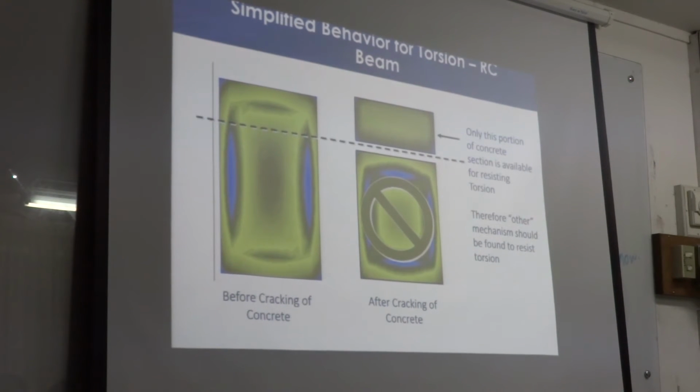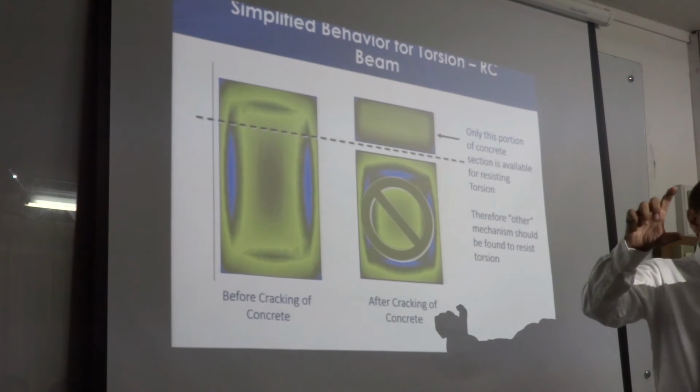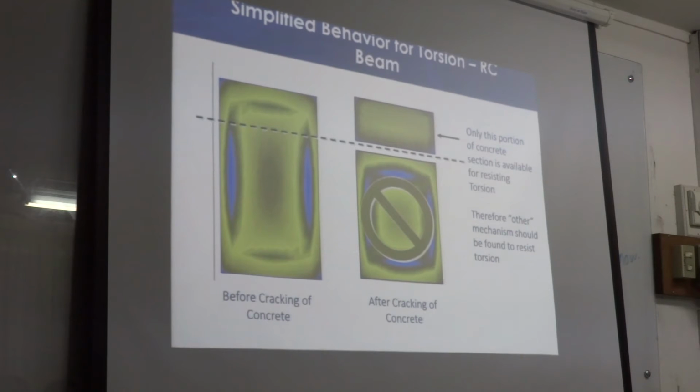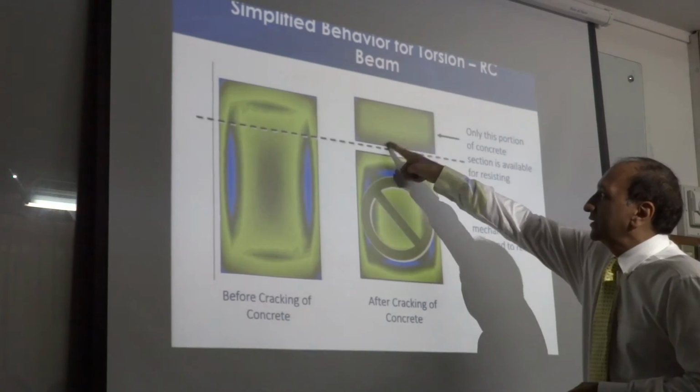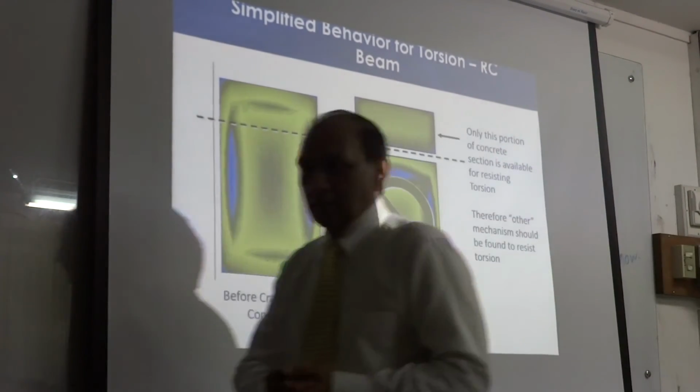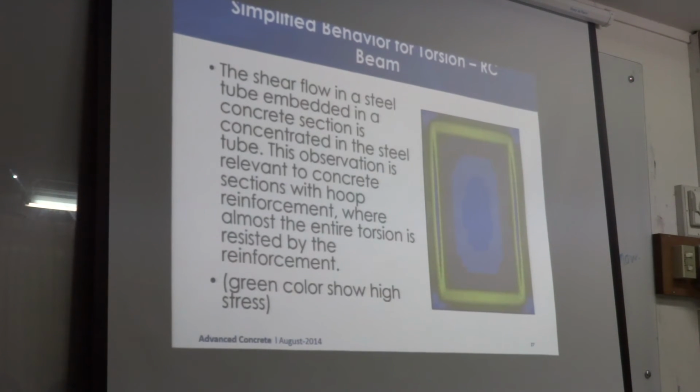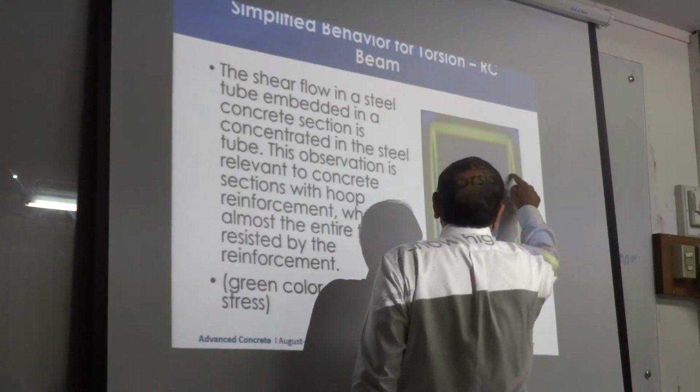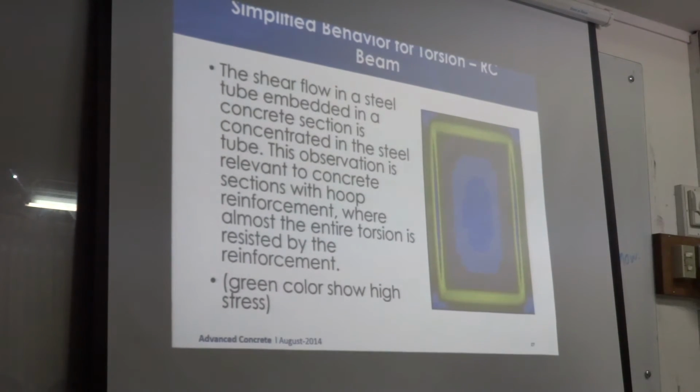Which basically means what? Basically it means that once you calculate the reinforcement, you provide the reinforcement, you need to check to make sure that all the actions that are coming can be taken care of simultaneously if they are coming. Correct? You may calculate the reinforcement individually, put them together, but the final amount must satisfy the requirement for all of them at the same time. Now, interesting thing is that if you provide a bar here, this bar maybe you design for tension. It also can take compression. So if the compression amount is larger than tension, you provide compression amount. If the tension amount is larger than compression, you provide tension amount. So we have to make sure that at each location, the reinforcement is sufficient to take care of all of the effects from various actions that can come there.